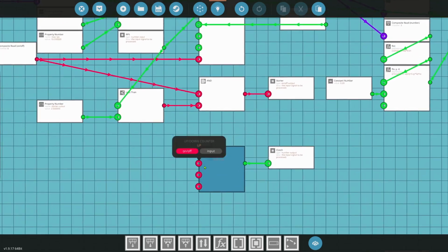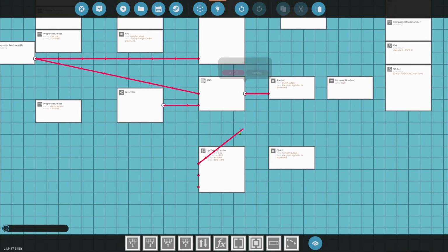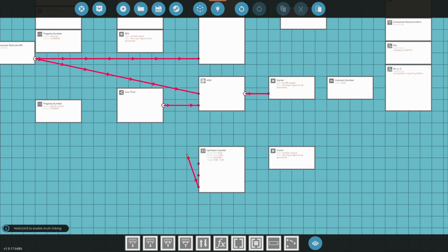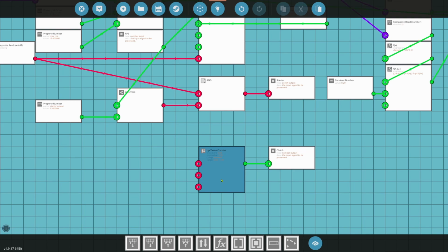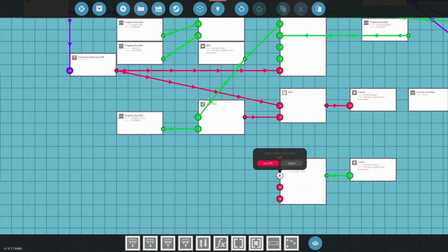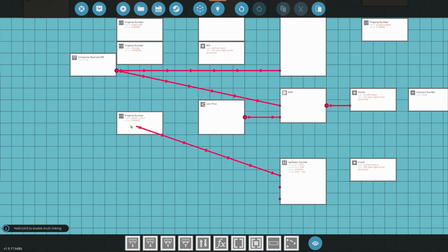All right, so now we need to come up with the conditions. When do we want to increase this value, which causes the power to pass through the clutch to our wheels, and when do you want to decrease it? And then when do we want it to completely zero the clutch out and make sure that the engine and the transmission are detached from one another, for example, when you're stopped at a stoplight. So the first condition is when do we want to engage the clutch?